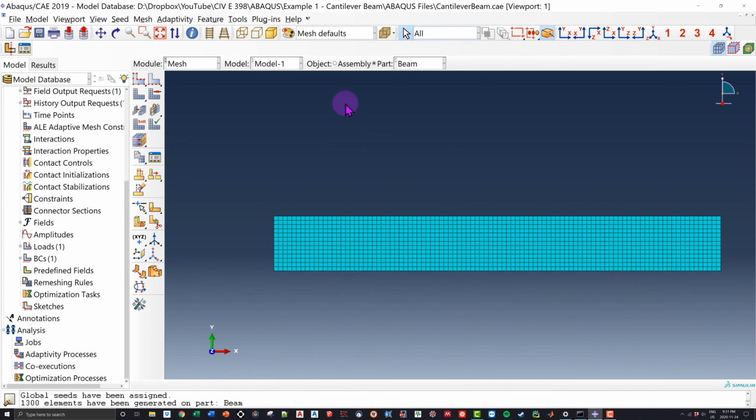So this is very important. If you guys don't define the mesh, your model won't run because you haven't defined any spots to actually do any calculations. You basically just gave ABAQUS a shape and said, play with the shape. Of course, ABAQUS doesn't know how to do that. It knows how to calculate things. In order to do that, we need to go into the mesh option. And at this point, we are good to go. Because if we look at what's after mesh, it's optimization. Again, I've actually never even used this. I don't have any idea when you guys would ever use this, so don't worry about that.